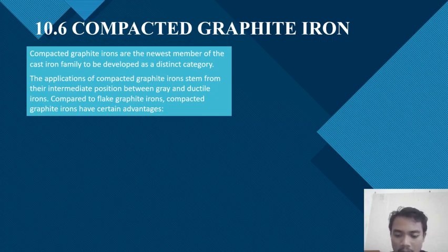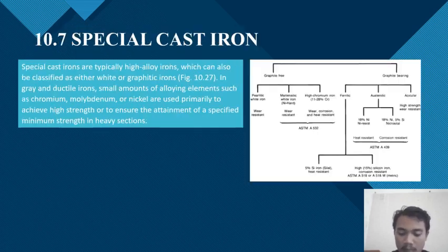The advantages of compacted graphite iron compared to ductile iron are lower coefficient of thermal expansion, higher thermal conductivity, better resistance to thermal shock, higher damping capacity, better cast stability leading to higher casting yield, the capability for pouring more intricate castings, and improved machinability.